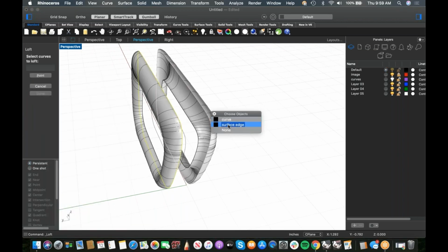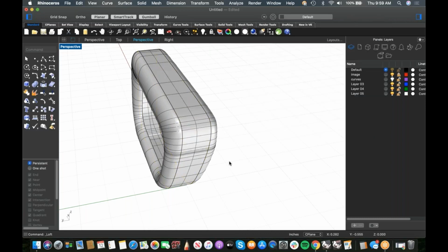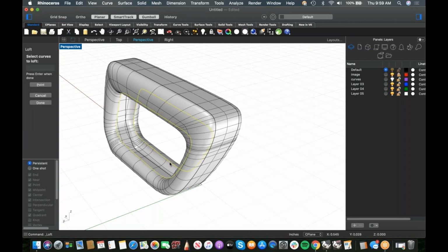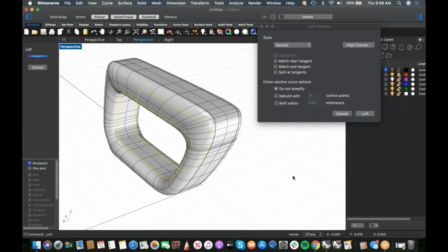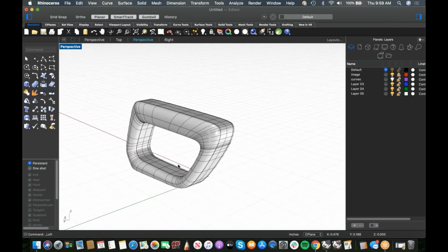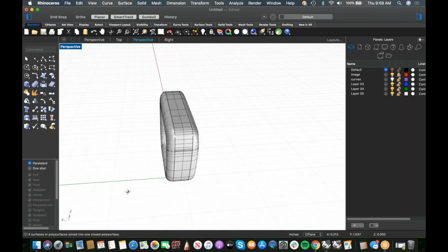So why did blend look so awful when we did it before? The reason was because the control points on the curves weren't in the exact same locations throughout the model. The loft was having a hard time figuring out where it should connect everything to.